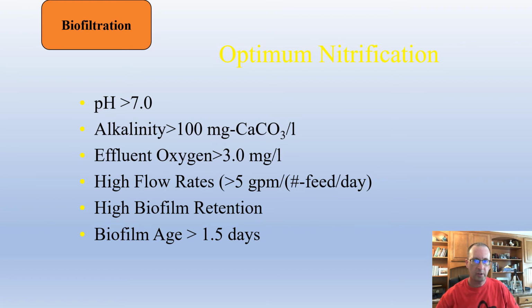This slide here really shows us the optimal formula for a good biofilter. Anywhere around neutral pH and plenty of alkalinity and a lot of good flowing water through the biofilter will help keep the bacteria rejuvenated. If you get the flow rates too high, or you just bombard the system with tons of food that some kind of settling chamber can't remove, then you're going to overwhelm your biofilter and it's probably